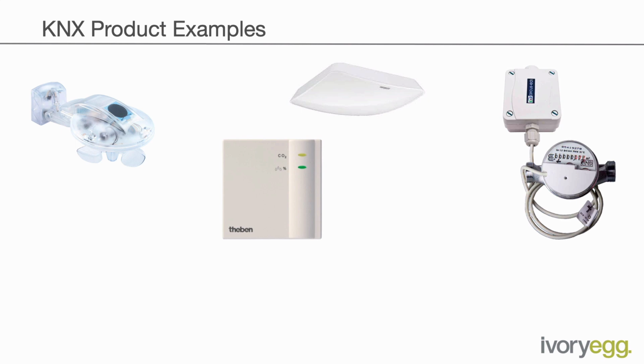We shouldn't have water flow because of the alarm set, which means the building's unoccupied. It's been more than 12 hours, so you've left the property. So let's notify the customer that they've got a leak. And let's also close a valve to stop the leak and prevent any damage happening. So using metering provides us with a lot more information and way to control the building.